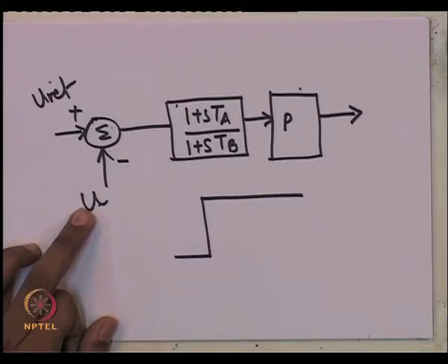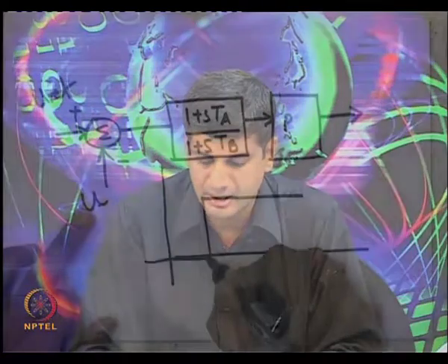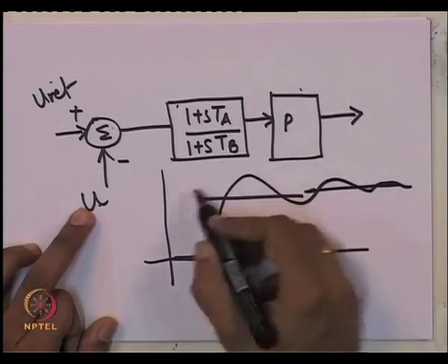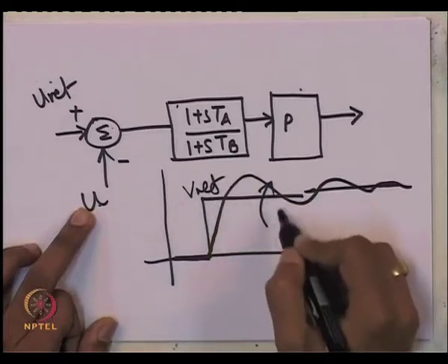It is a fairly complicated way, because you will have to actually solve all the differential equations either numerically, or if we linearize it around an operating point, you can even do a linearized kind of analysis. What I want to say is that eventually the U in an automatic voltage regulator is going to be determined by a fairly complicated set of dynamical processes. So, eventually a response is going to be something like this, it could be something like this. For a step change in the input, for example, if this is your voltage reference, your actual V could be like this.